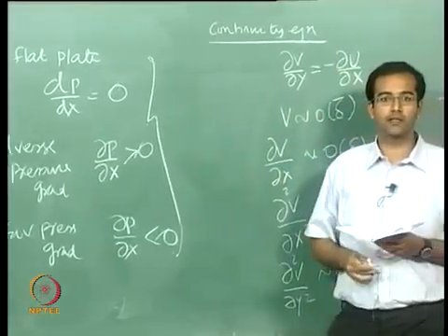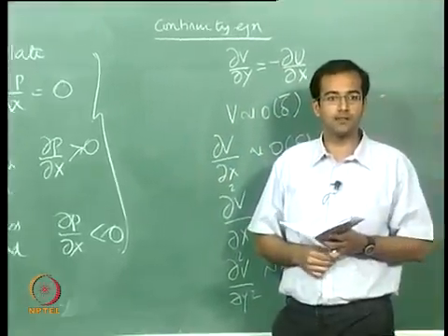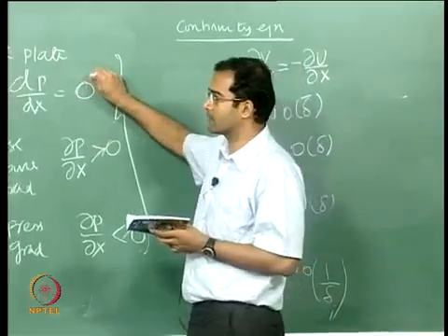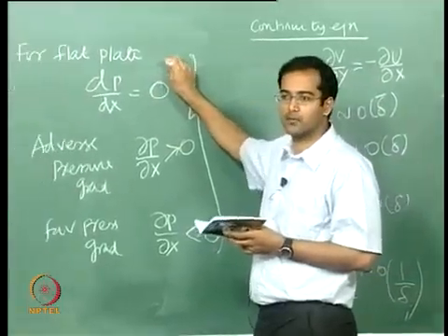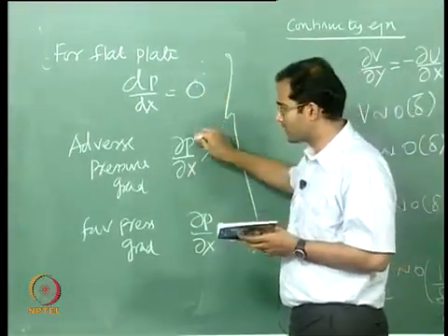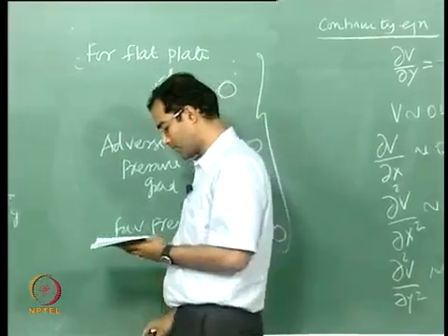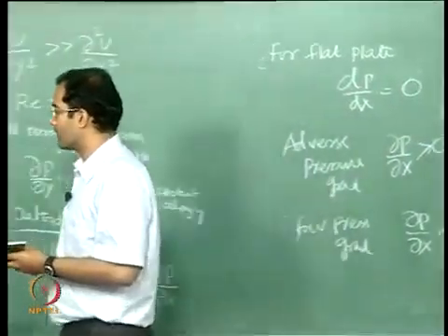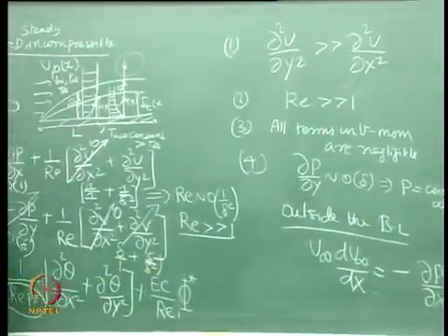If u infinity is equal to a constant, then this is the best approximation, it is going to knock off the pressure term completely. Otherwise you have to consider either of these cases. So that is the approximation to the momentum equations.